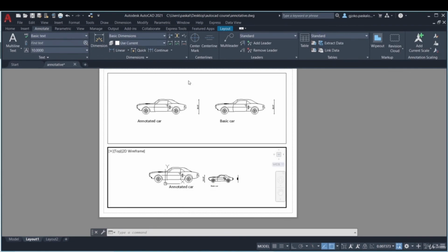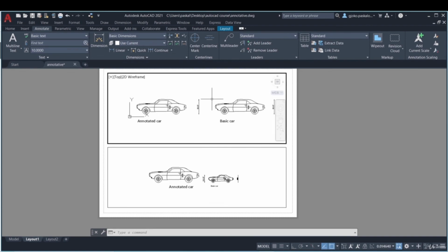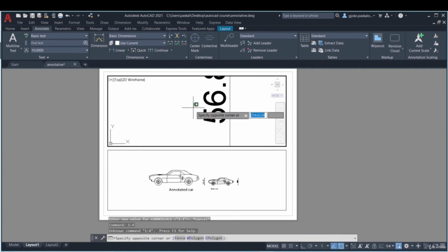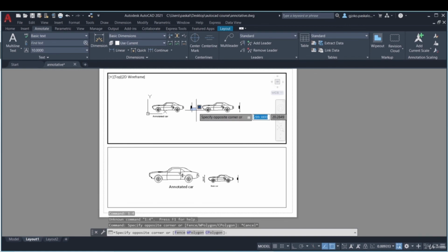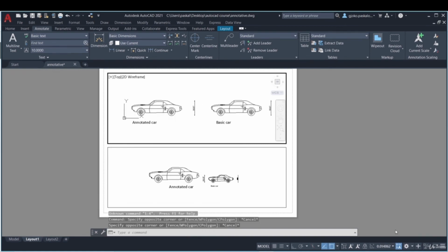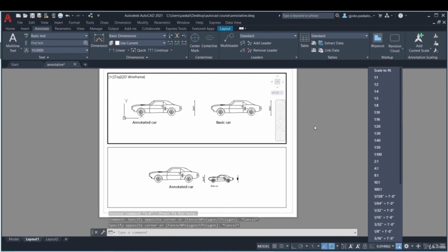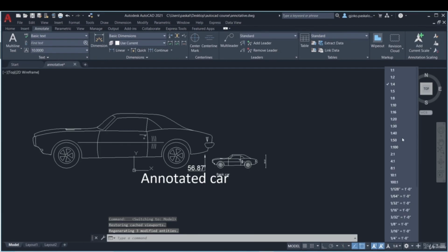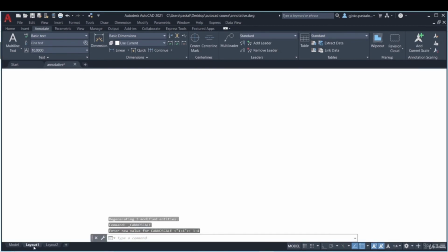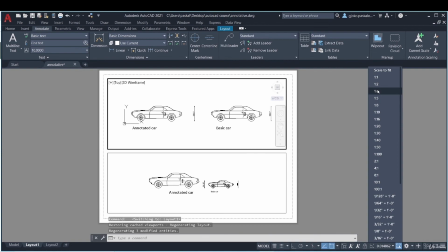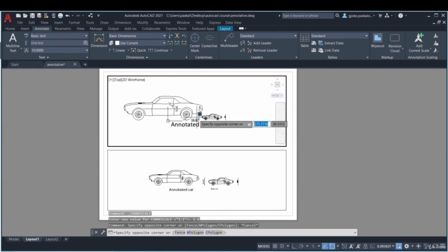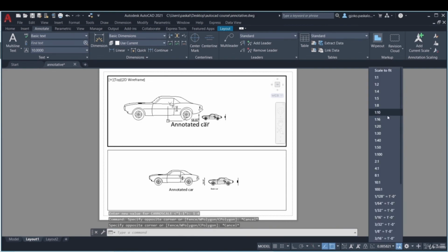So in this viewport we can add a different scale appropriate to that viewport, and let me try this scale. Let's zoom out. Okay, it actually didn't work. So we have to apply the same scale in the model, so the changes will apply. Okay, let me go back to the layout and try it again. Same scale, and here it is. The drawing actually adapts to the scale.